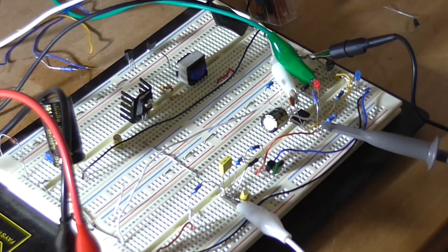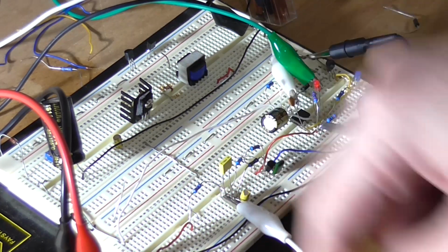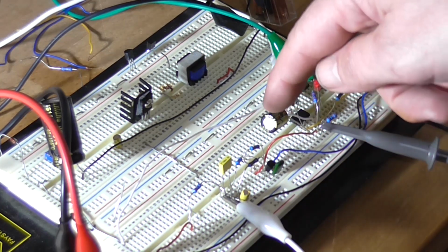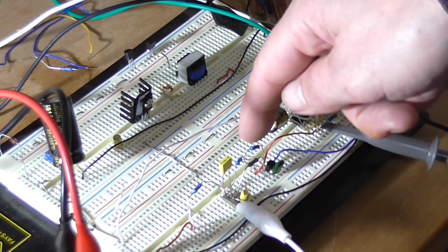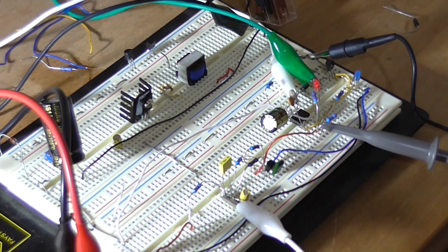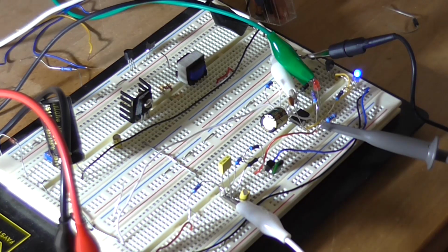Well, anyway, messing with the resistor values further, like the resistor here for the microphone, lowering it made no difference. Increasing and lowering that 100K resistor there makes it too sensitive that it just makes it permanently on. However, if I was to talk a little bit louder or closer to the microphone, hello, hello, it will eventually click on.